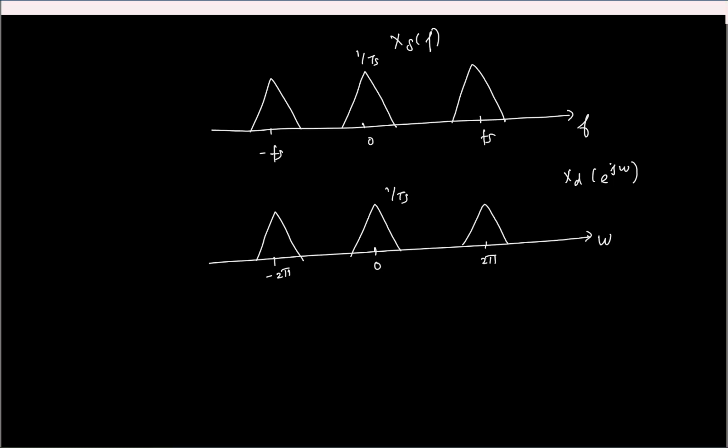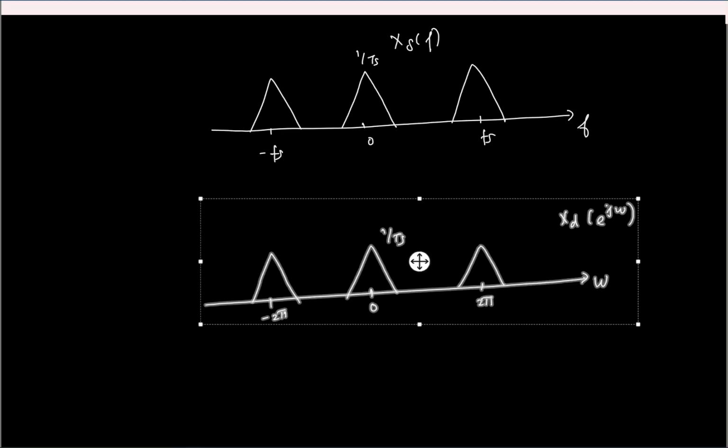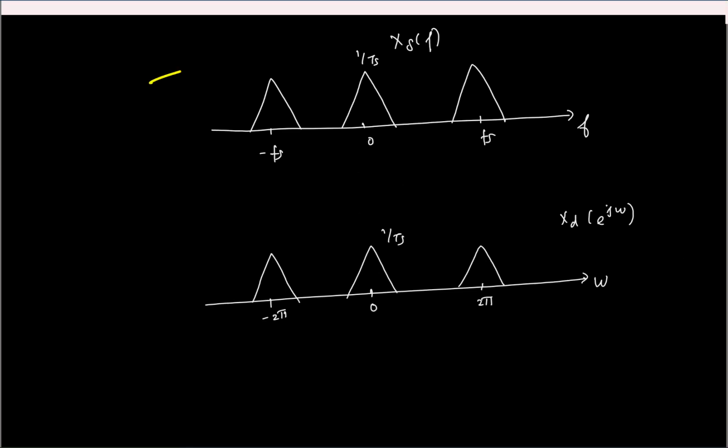Let's reprove the obvious. Let me push it down first. So let us say here I reduce the sampling rate fs. I keep reducing the sampling rate fs. What will happen? These replicas will start to come closer, and beyond a point, they'll start to overlap like this, and the signal gets corrupted. The technical name is aliasing, and we'll come to that. If I call this minus b and plus b, what is this frequency? Fs minus b. So to prevent aliasing, fs minus b should be greater than b. This is what Nyquist told us centuries ago, or maybe decades ago.